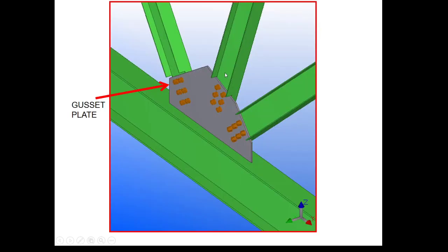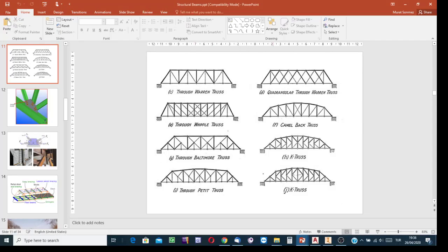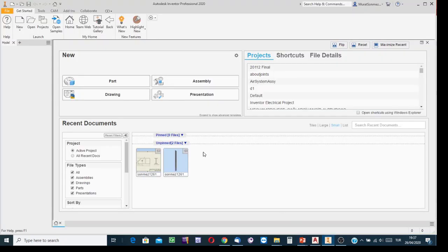So, well, at the sketching stage, in using the design tool of Inventor, the first stage is the sketching stage. In sketch mode, as the sketch, draw the lines and say that those lines are just the lines joining the centers of the cross sections of the members. Okay, draw this line, draw this line. These lines in the schematic drawing correspond to the lines, repeat again, which join the centroids of the members. Okay. Yes, now, after this slightly detailed explanation, during the application, you're going to see what I mean much more clearly.